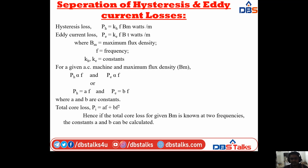And the eddy current loss is directly proportional to the square of the frequency. So we write these equations as P sub H, the hysteresis loss, equal to A into F, and the eddy current loss equal to B into F squared, where A and B are the constants.